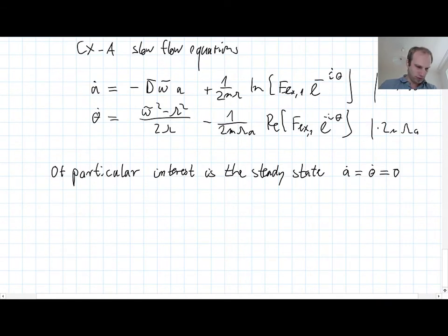Now if we do this multiplication here, then what we get is this. The terms that we get here, if we multiply by m omega and exploit also that this 2d omega tilde is actually small d over m, so the effective damping, which is composed of the underlying linear damping and the equivalent nonlinear damping.